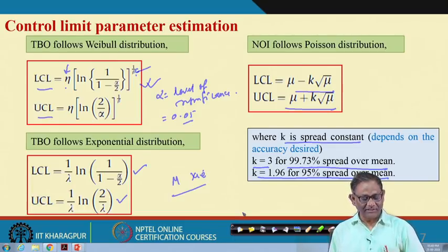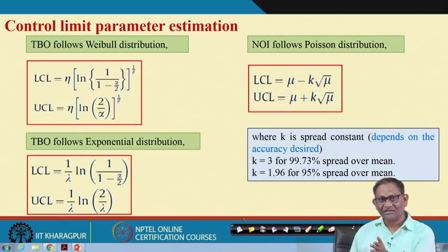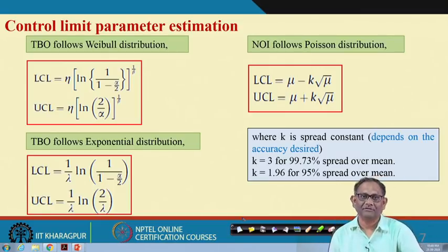So, essentially, if I know the LCL and UCL, and the CL is the mean value, then your control chart is designed. Your only remaining task is to collect the data, plot the observations on the control chart, and then see the patterns.